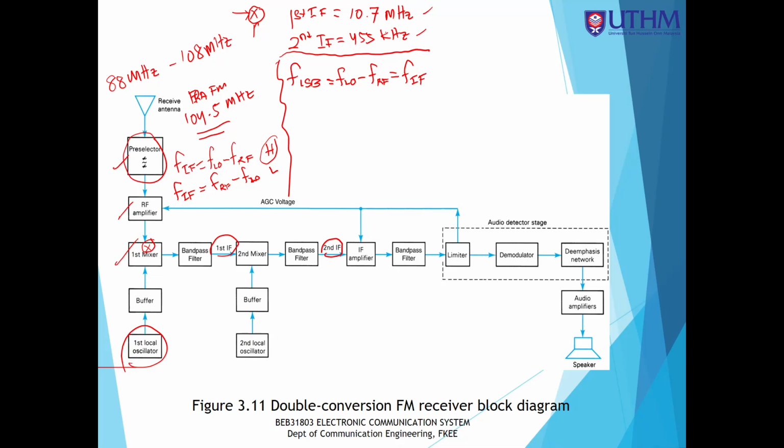Why is it like this? Because when we do down conversion, we are planning to down convert a high frequency into a lower frequency. When we perform down conversion, what we actually want is the low frequency, not the high frequency. So the upper frequency produced by the mixer converter, the USB, is FLO plus FRF. The signal that we want to produce is the lower one.